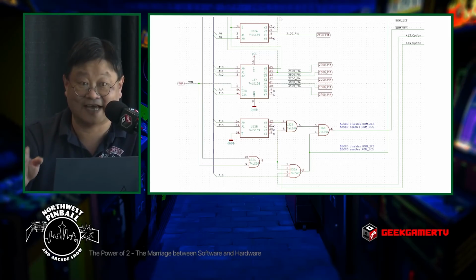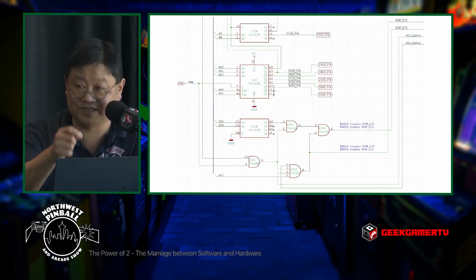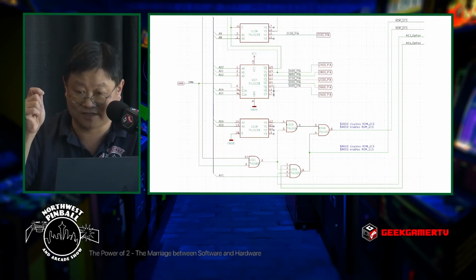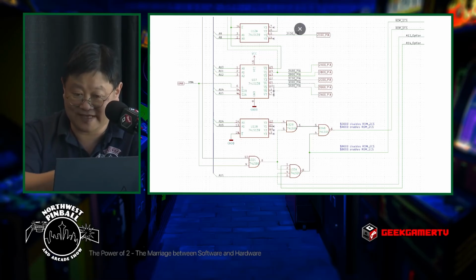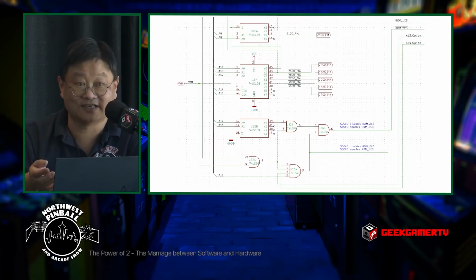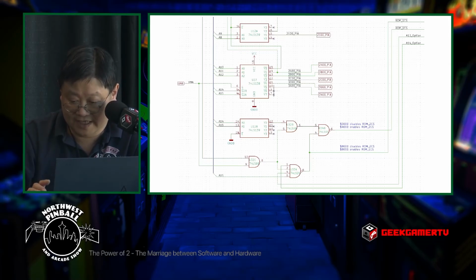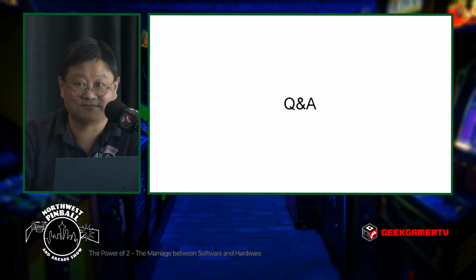I'll tell you now, that's a latch. It's a specific thing: if you want to get a solenoid, you touch 2200, you write the bit pattern that you want, and those solenoids from 1 to 8 get activated. And 2300 is not used. That's address decode. You've got to sit down and work through it, you've got to get all your bit patterns. But once you look at this, you'll figure, oh, that's how it's supposed to work.